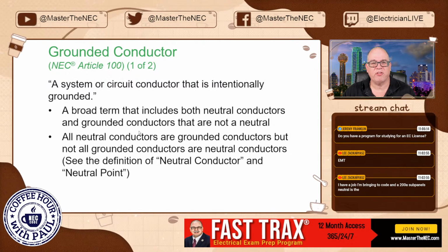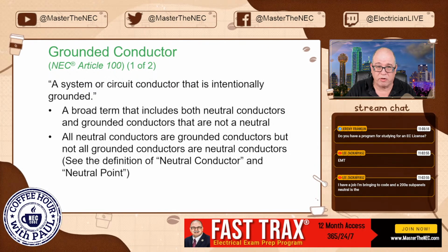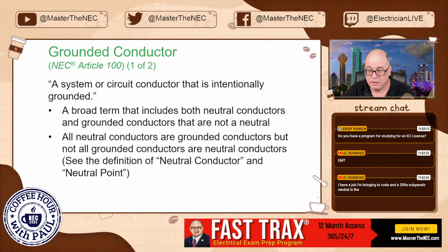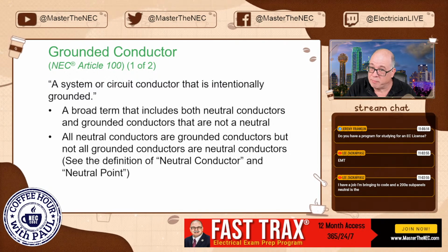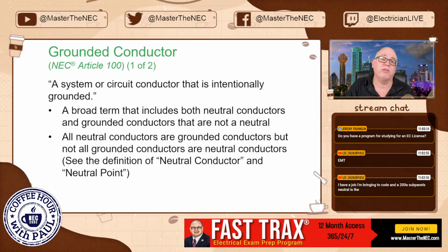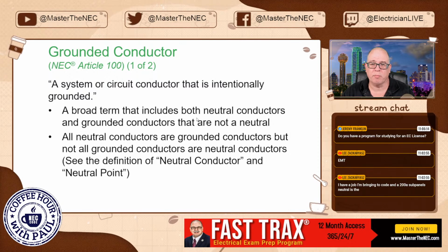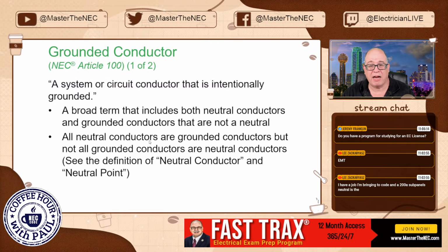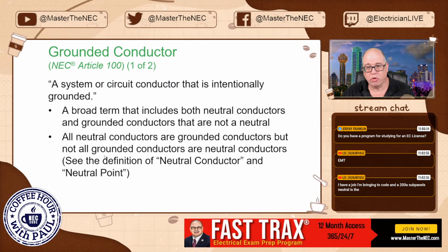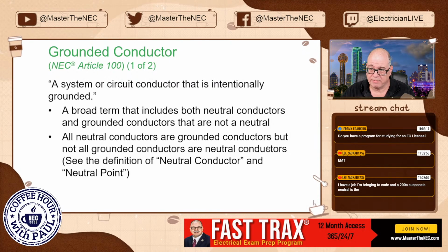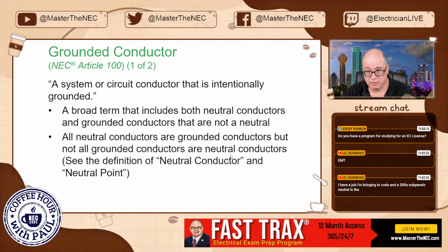Grounded conductor: a system or circuit conductor that is intentionally grounded. So anytime you see a conductor like that, it's called the grounded conductor, okay? It's not always a neutral, but if it's intentionally connected to ground, it's always going to be considered a grounded conductor. It's a very broad term that includes both neutral conductors and grounded conductors that are not a neutral, okay? All neutral conductors are grounded, but not all grounded conductors are a neutral conductor.